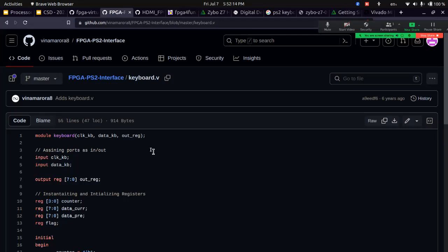On the opposite side, this 0/1 can be understood as an interrupt. And the processor, in every fetch cycle, like how do you detect an interrupt? In what interval? So what we did is that at every fetch cycle, the processor will see whether there is any interrupt, maybe a timer interrupt or keyboard interrupt.